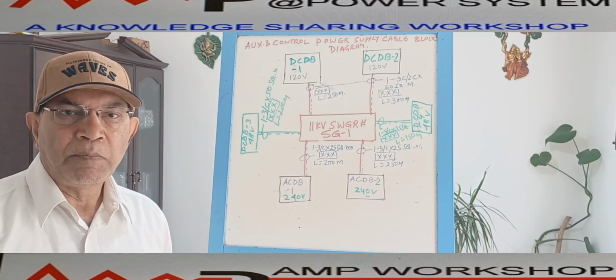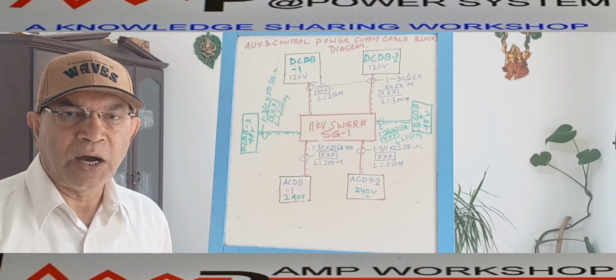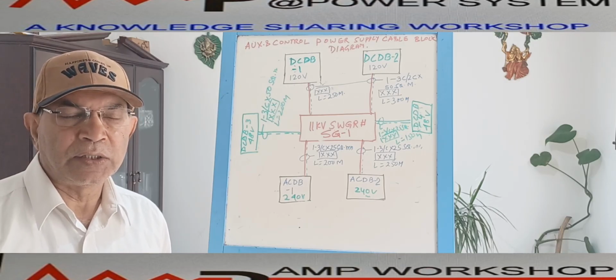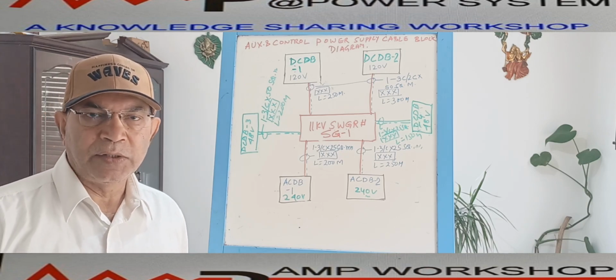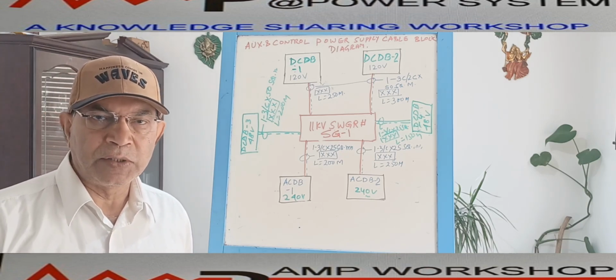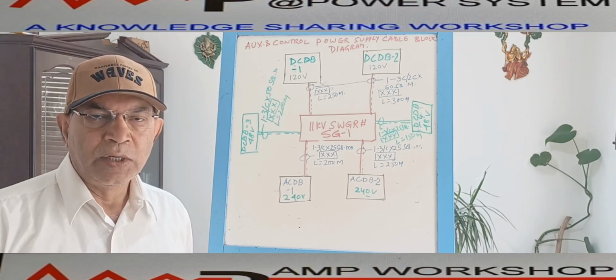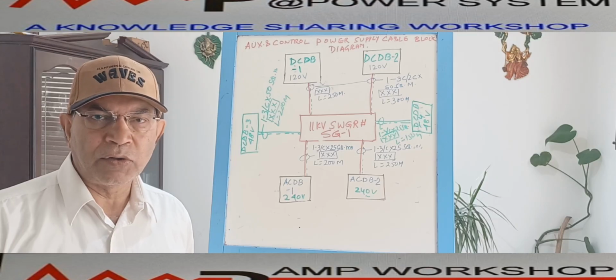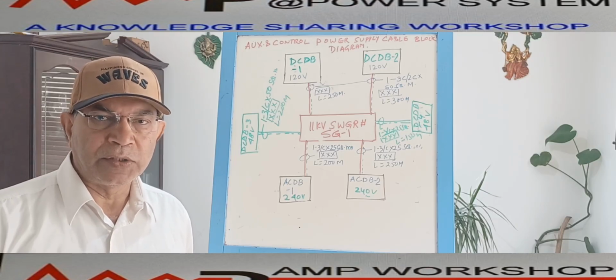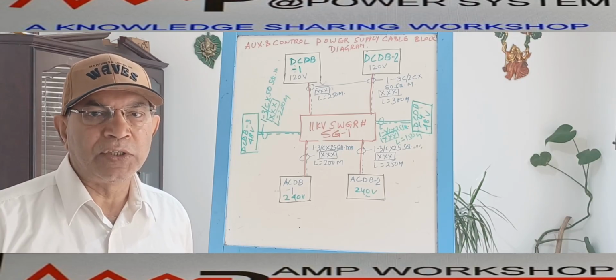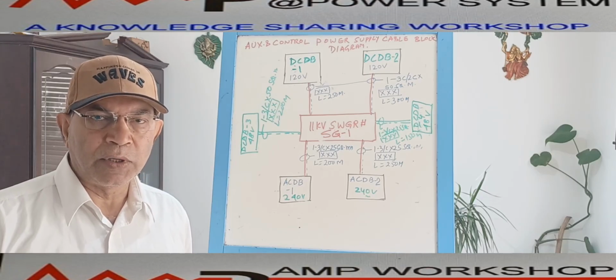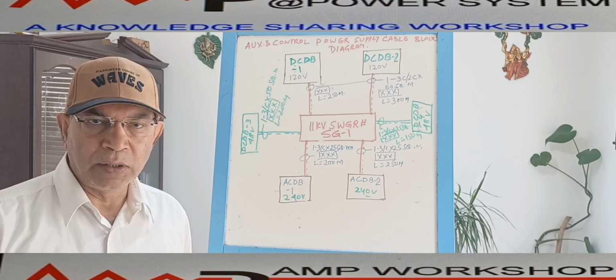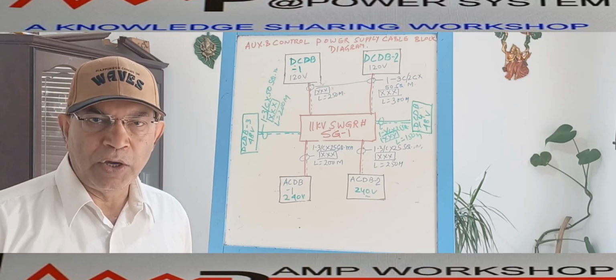Out of these, power devices like circuit breakers and isolators need a slightly higher voltage power supply because these devices need a good amount of power, as there are actuators and DC motors. That's why for those power devices, auxiliary power or control power you can say, we provide through a 120 volt DC supply. Now this 120 volt DC supply is used for the circuit breaker control, like closing operation, tripping or opening operation, then various auxiliary relay operation.